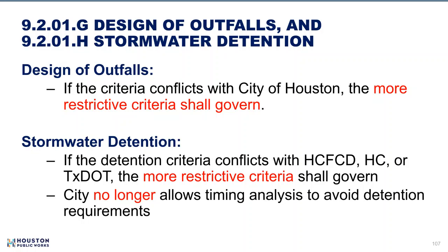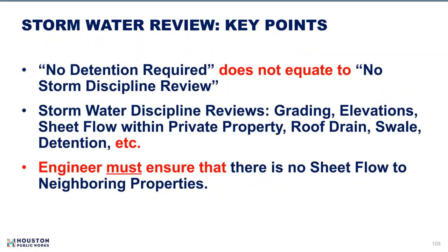One of the important things is that the city no longer allows the timing analysis to avoid detention requirements. Way back, before this year, before last year, we had a lot of analyses using the timing analysis, and they would show zero detention required. Most of those projects were right next to the Bayou, right next to Lake Houston. So we have so many of those in the system that did not require any detention way back.